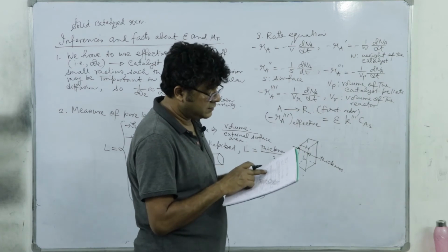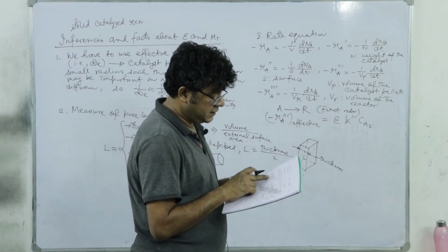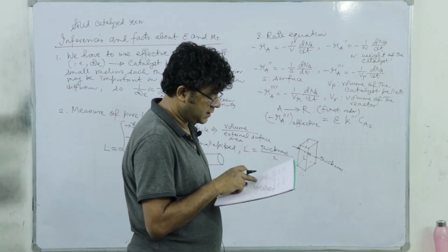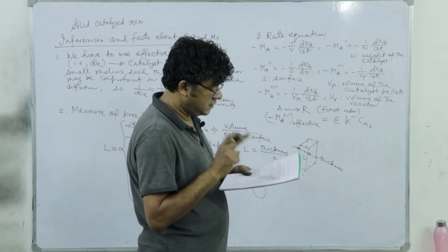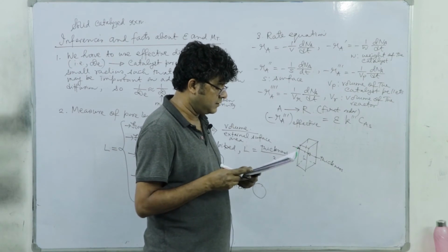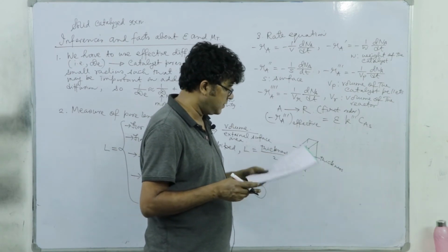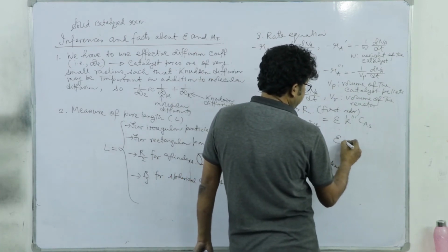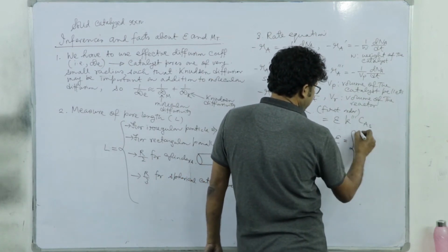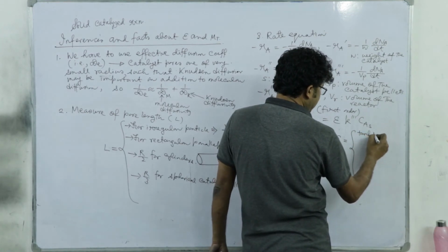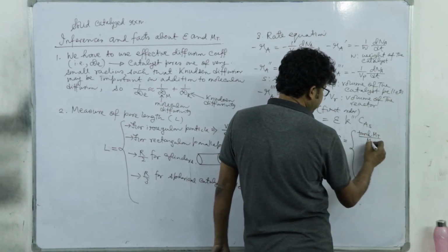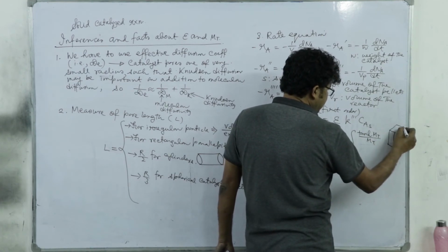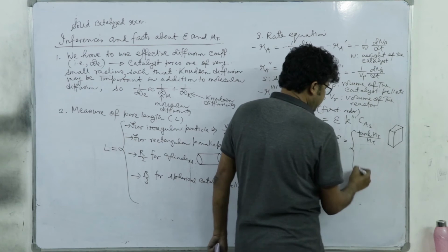In the handout, it is wrongly stated initially in equations 23 and 24. There is a typo: it is written as 4 prime, but actually it is 3 prime, right. So, for these cases, epsilon is equal to what? It is equal to tanh(mt)/mt, the same expression as for the rectangular parallelepiped shaped catalyst pellet.